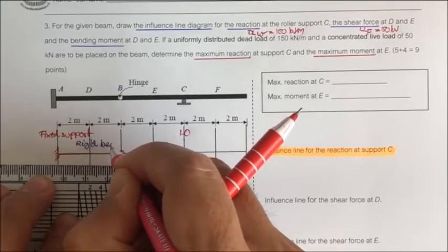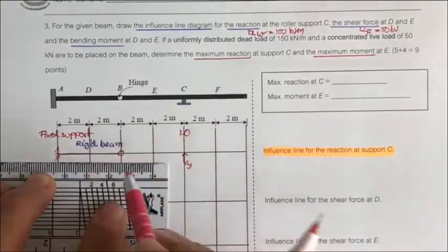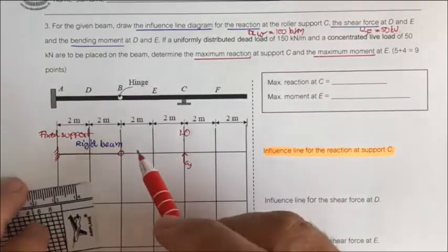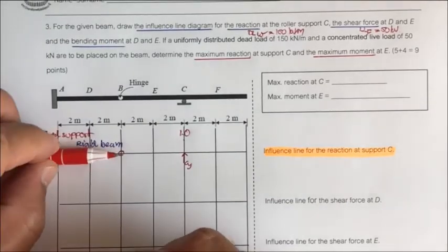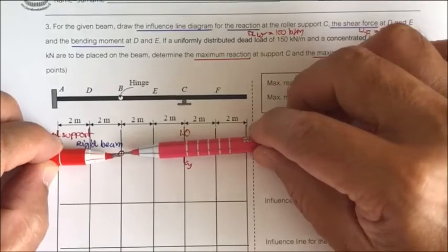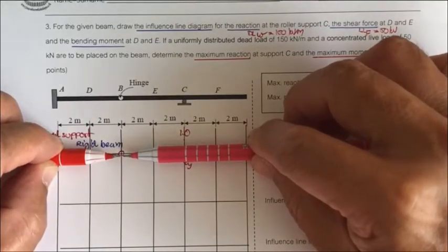When all portions of the beam are rigid beams, the change in the shape of the beam will be linear. Since this one is fixed and this one is the hinge, you put the C sub y in that direction.